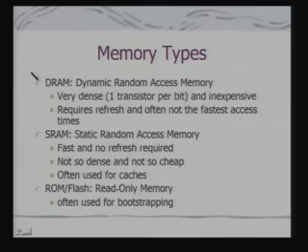Further, we can look at their divisions into dynamic RAM, DRAM, static RAM, that is SRAM, and ROM or flash, which are read-only memory, and read-only is often used for bootstrapping. In fact, flash has some characteristics so that we can even do in-circuit writing as well. So, they are not strictly read-only, but their primary usage in applications may be for read-only purposes. Here we have a comparison of their characteristics.